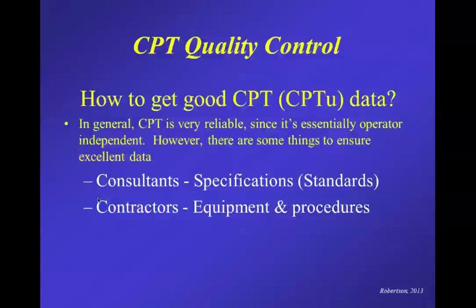So we're going to talk about CPT in soft sediments and the accuracy of the measurements, and of course one of the downsides of the standard penetration test is if you encounter a very soft clay, then it's not unusual to get a blow count of 0, where the sampler penetrates under its self-weight. And so in a way that's infinitely inaccurate, and so you have really no sense of how strong that material is other than the fact that it's soft.